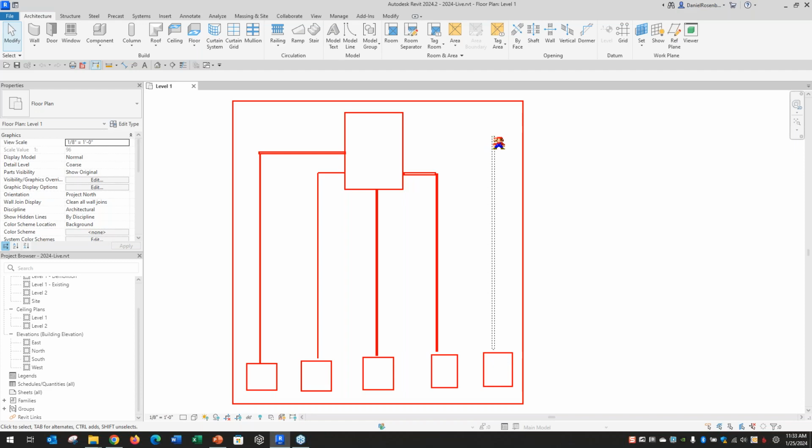So as I'm drawing this here, we've got a lot of users here. They're all connected. What's going to happen is the project manager, or if you've got someone who sets all your projects up, project comes in the door, they're going to save the Revit model onto the server. They're going to enable worksharing, and then when they save it, it will behave as the central model. Then, let me mark that. So let's call that central.